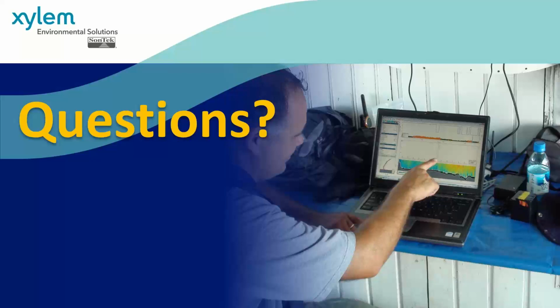If you do have cell service, or any other type of internet service wherever you're measuring, that will be good for you to tap into the network RTK service. Once you have that, you can just use a rover and take your measurements. You don't have to worry about a base station.